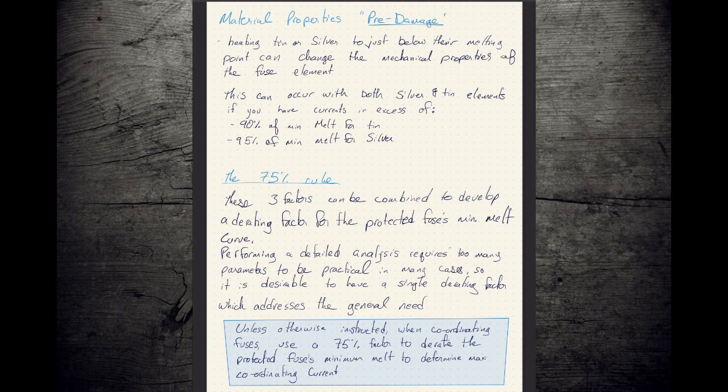This is made out of steel, and the steel is super hard, right? Because it's a cutting tool. So that steel is really, really hard. If you take a file and you heat it up just below its melting point and then you cool it down real slow, you'd probably be able to bend it with your hands when you were done. You'd have taken all of that hardness and much of the strength out of that steel.